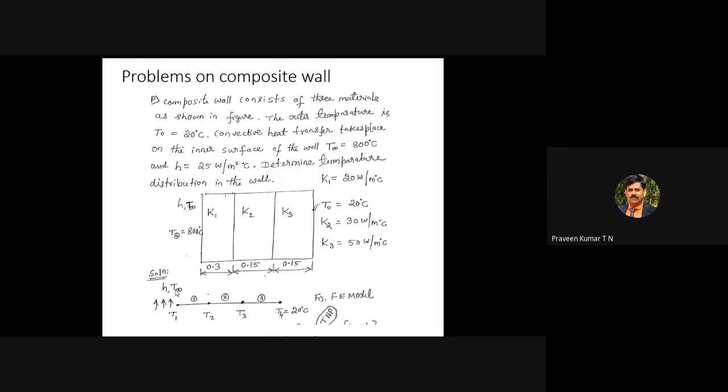So if you model the red hot rod as a finite element, the temperature of the rod may be 500, 400, or 300 degrees Celsius. The surrounding temperature may be 25 or 30 degrees Celsius, because heat is transferred from the red hot rod to the atmosphere by the convection process. Because of the convection process, the surrounding temperature is given by T infinity.